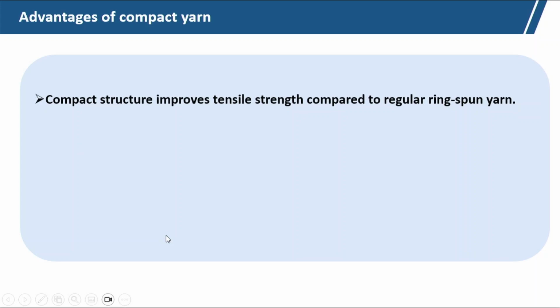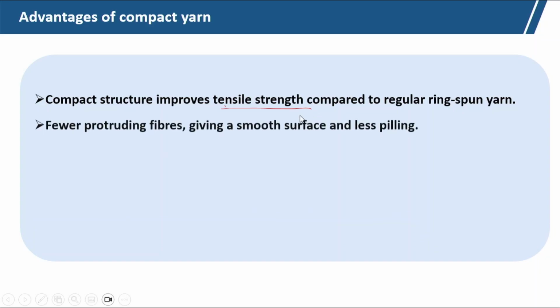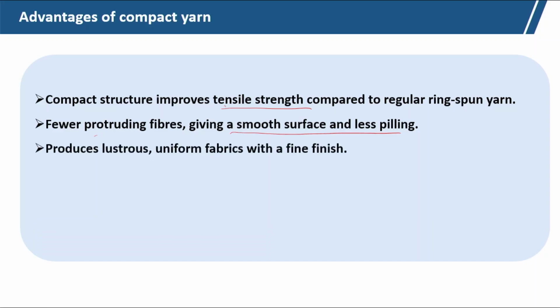So, the advantages are: it has improved strength compared to a regular ring spun yarn, fewer protruding fibers giving a smooth surface and less peeling, and it produces lustrous uniform fabric with a fine finish.